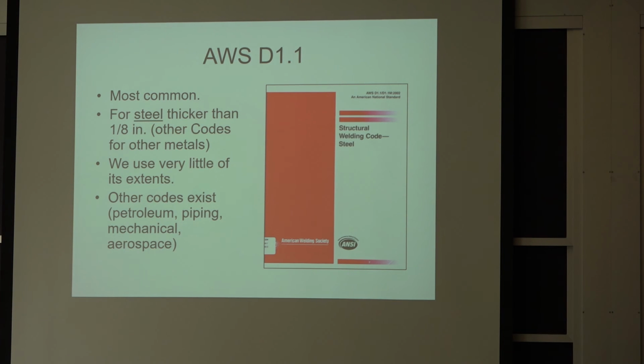So it's a very, very good guideline, but when you go and ask for something to be welded, just like those arms, unless it's calling for the welding code as the standard for quality and how it's been done, then people can build it other ways, especially if it's done overseas. So even though this material on how to qualify your procedure, qualify your welder, do the welding, and inspect the welding is all there, it needs to be called for a lot of times.